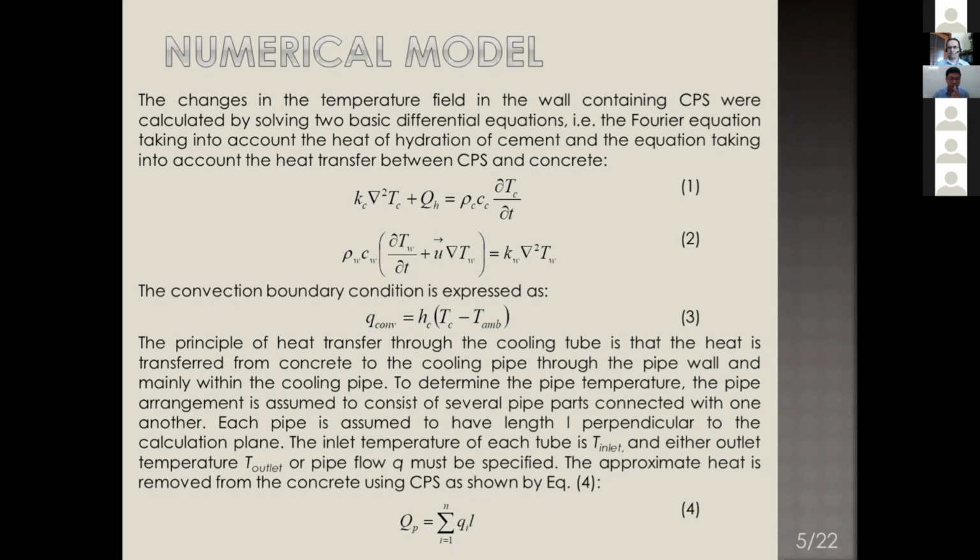You can see from the equation the convection boundary condition is expressed as the principle of heat transfer from concrete to the cooling pipe, through the pipe and water within the cooling pipe.